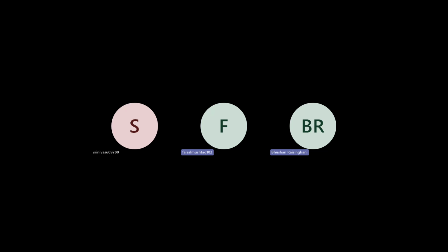So plan aspect ratio is basically mentioned nowhere; no textbook covers it except in architecture. But the IS code has told us to have a plan aspect ratio of 3 and 5. So for tall buildings, in code 16700, if the plan aspect ratio is more than 5, then we consider it a flexible building, and we should consider all tall building criteria for that.